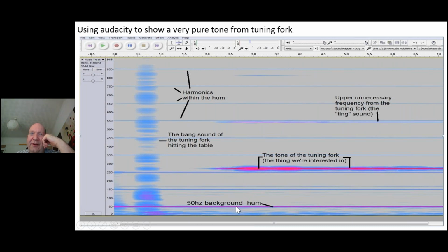Now, this 50 hertz hum, it took me ages to work out what that is, but that's an artifact of the computer. That's inside the transformers, flashing backwards and forwards, making an alternating magnetic field that's also superimposing on top of the electrons in the wires its own 50 hertz hum. It's quite hard to get rid of that, but in really expensive stereos, they use a thing called mu metal, which is an alloy that basically confines magnetic fields.